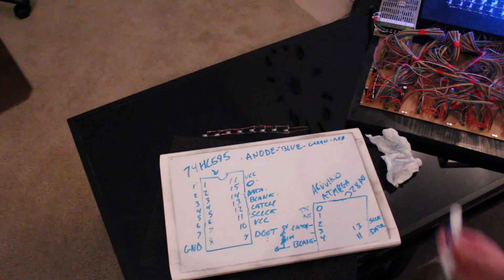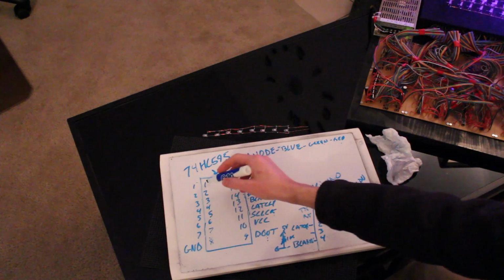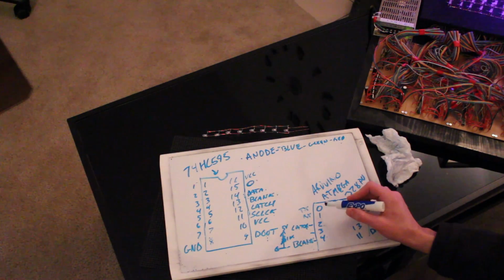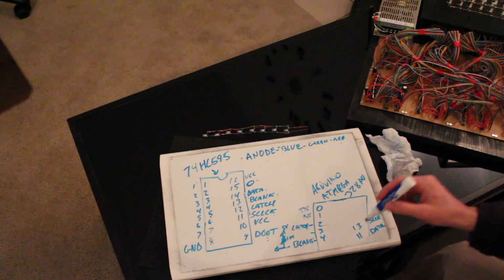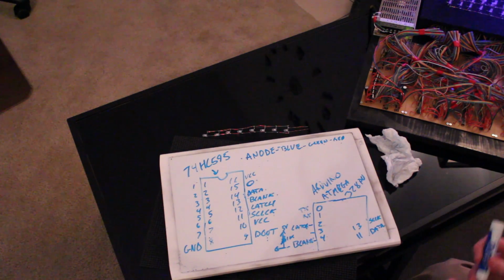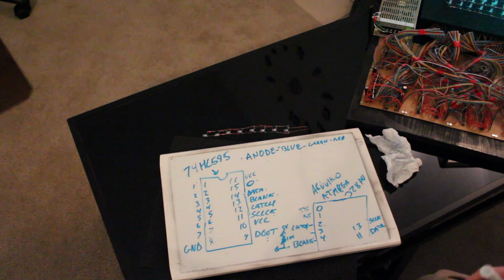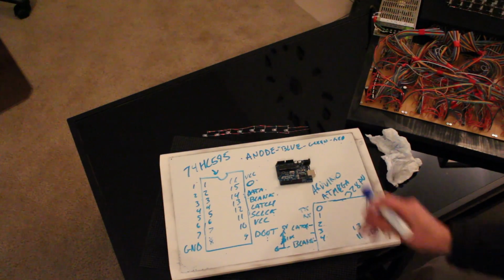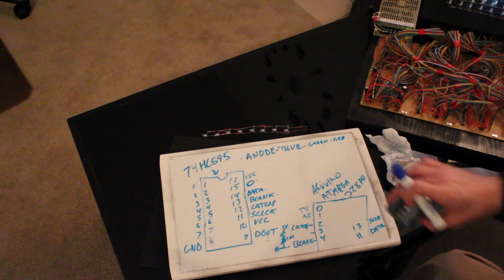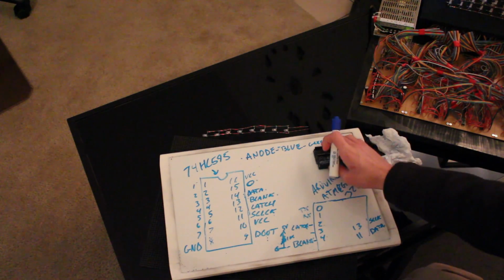For example, TX, if you started at pin 1, would actually be pin 2, 3, 4, 5, 6, and then it wraps around to the other side, which I don't know what those are. But anyway, not a big deal. You can easily find out what the pin mapping is if you decide to do a standalone chip like I did here.